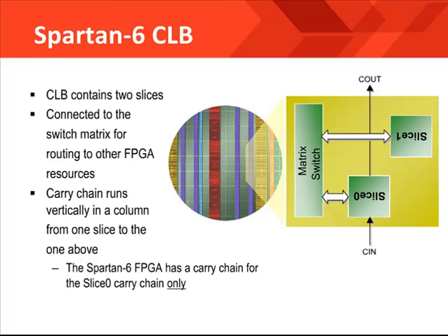While each device family is offered with a different number of CLBs, determining which density is right for your application often requires you to at least synthesize your design before choosing an appropriate density of FPGA. Only with some experience can you properly estimate how many slice resources will be necessary for your design without at least synthesizing the design first.